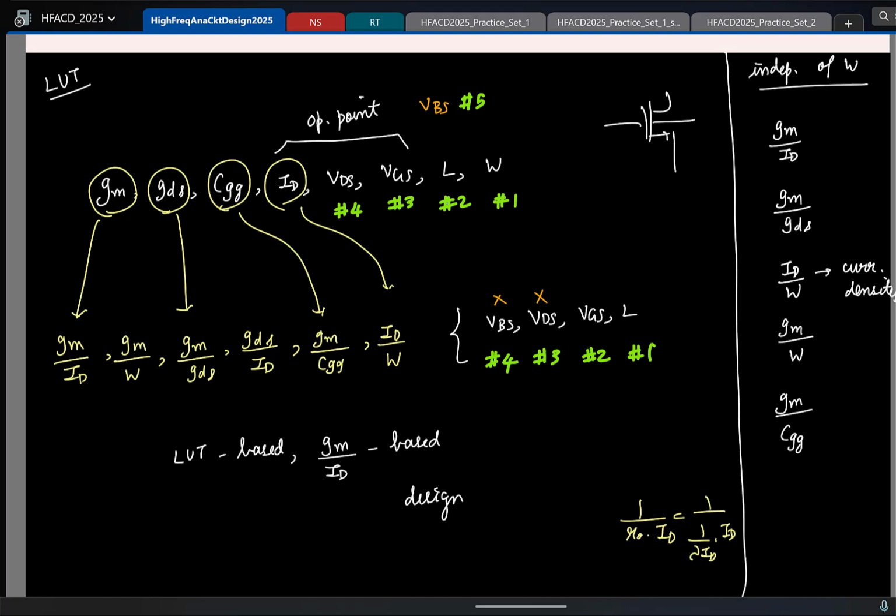Cool. So now if I had to list down the steps you have to follow to generate this lookup table, I just have to sweep length and VGS. Again, you have to generate this lookup table for both NMOS and PMOS, because you will be using both transistors. So it's essentially like having a for loop. I'll start by sweeping the length. You start from, let us say, the minimum possible length, 2 times the minimum length, and so on. Ideally, as many different lengths as possible.